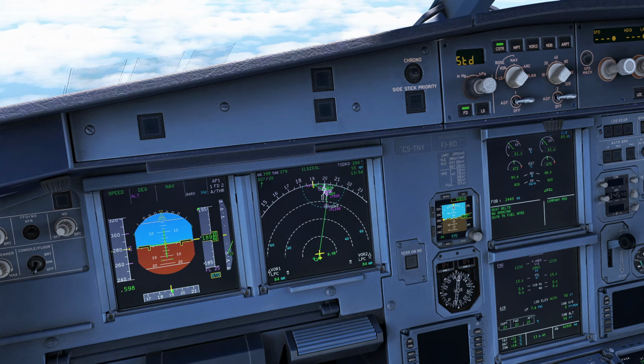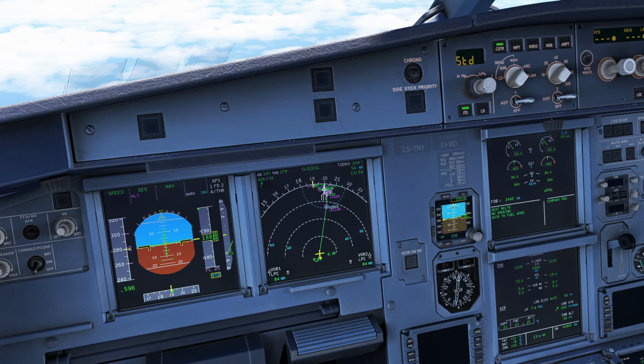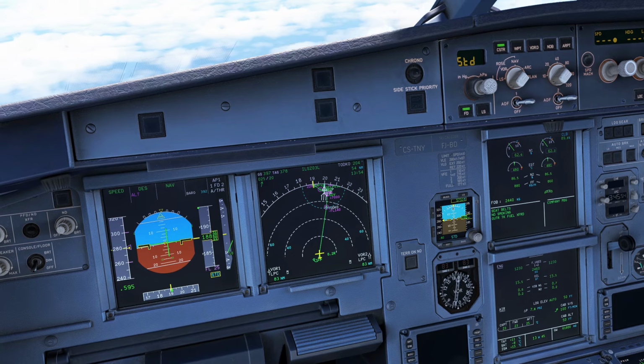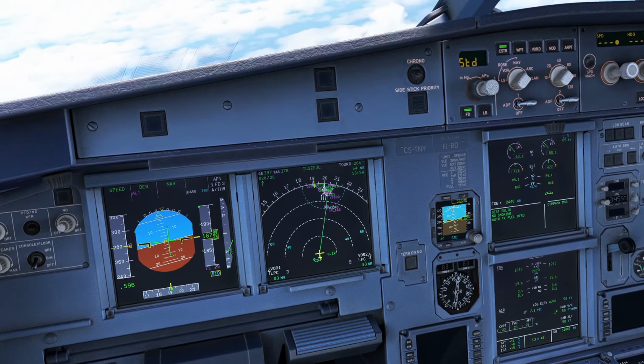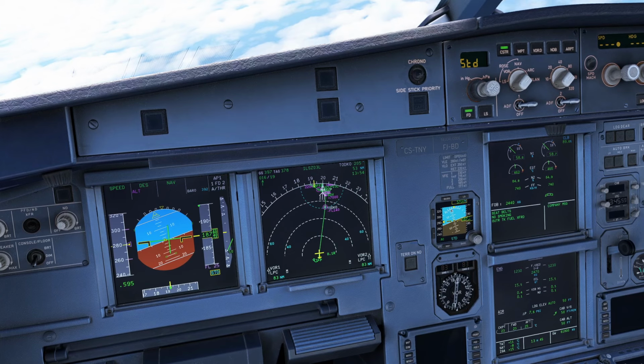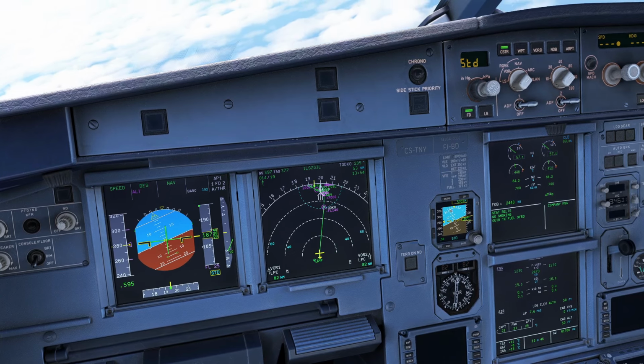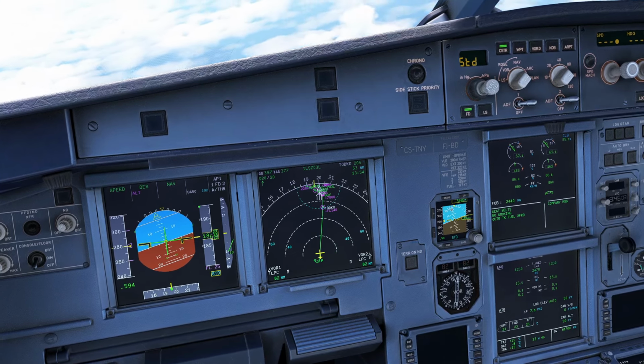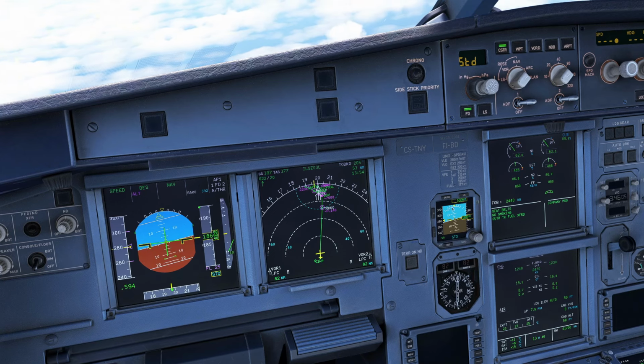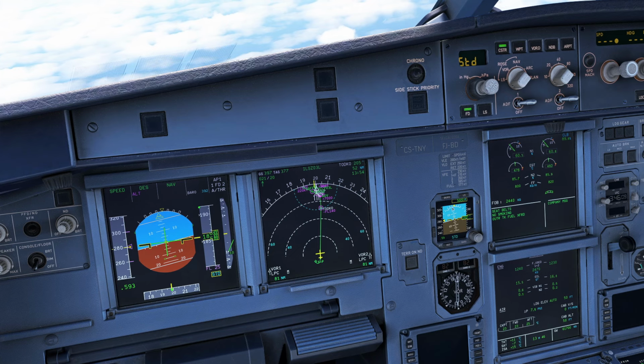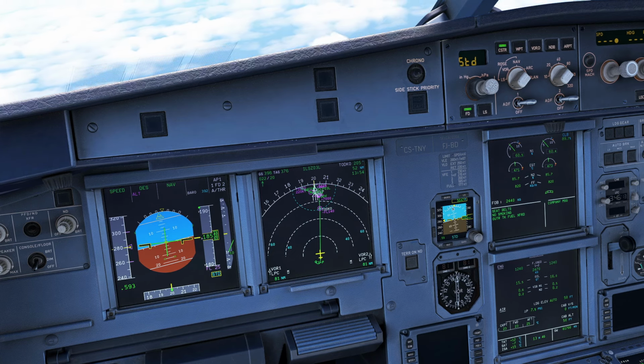The pilot flying must choose based on ATC conditions, weather, runway length, terrain, and operational preference, which kind of approach technique should be followed upon reaching the final descent point and also during the approach. Many airlines prefer early stabilized approach for SOP standardization and also safety margin.